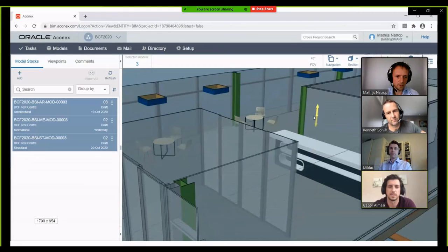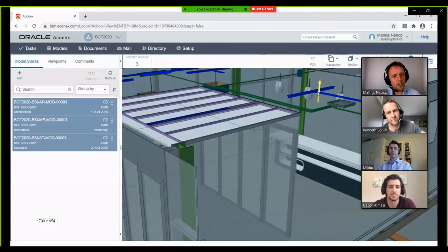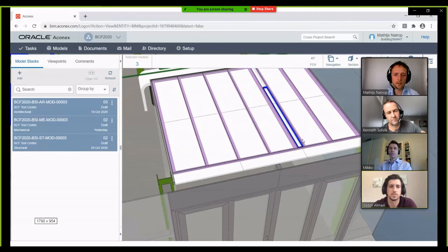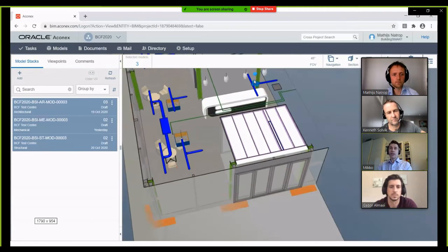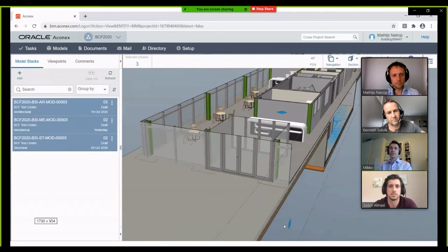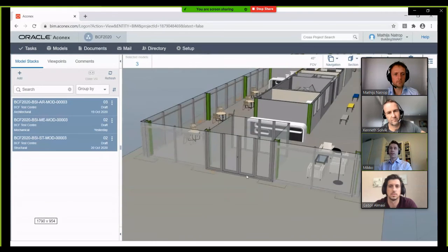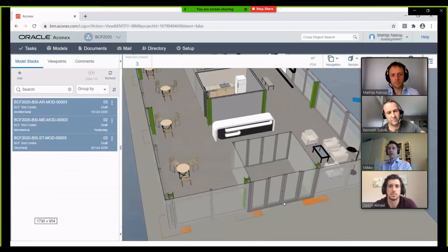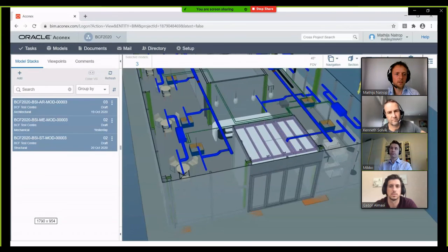The viewpoint, yeah. Okay, Miko, what do you think is powerful about this workflow? What you are saying and showing now is that these clip planes, when they are saved in this BCF, make it very easy to see a portion of the building. So a better understanding of what and where the issue is.